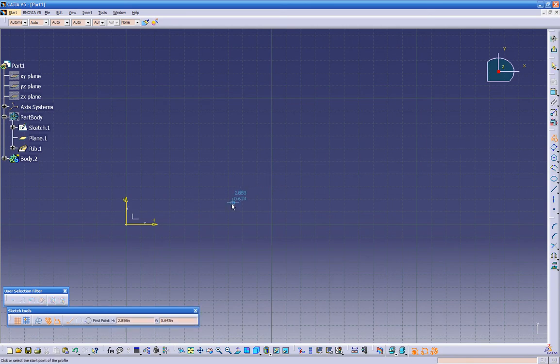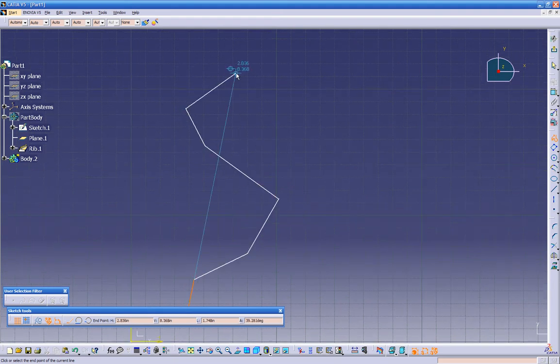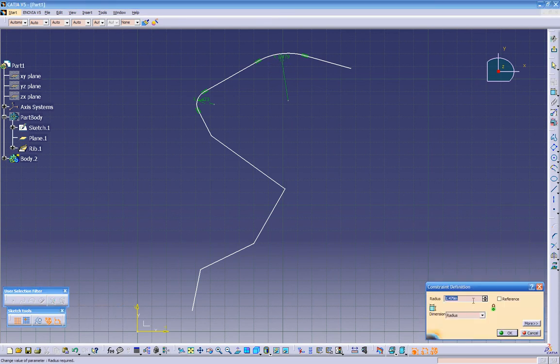Let's create again a shape. We're not gonna put corner radius this time because, click escape. We want to try the corner radius option again. So click, if you double click, we'll just stay active. So you can put a radius over here. We can put a corner radius over here. And we can change the dimension by just double clicking on it.